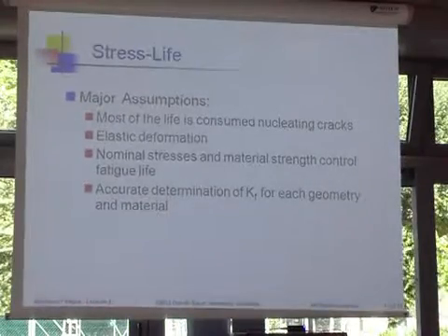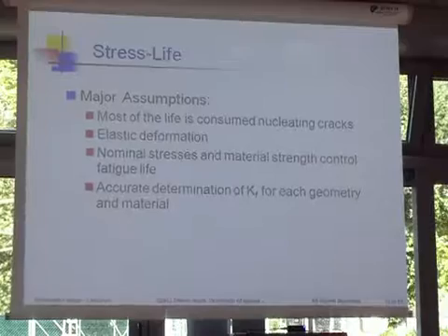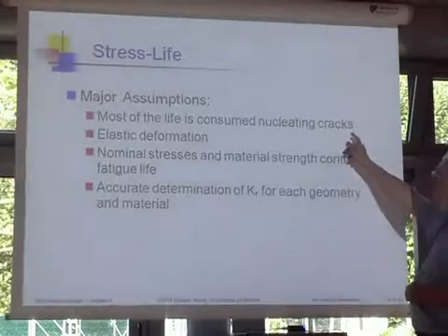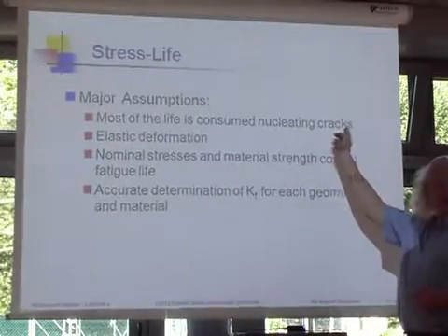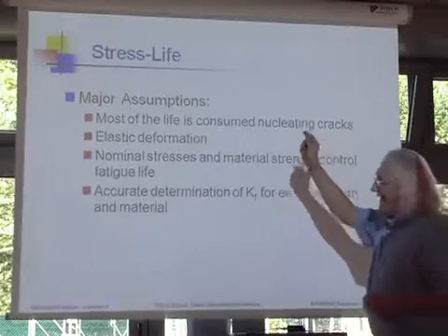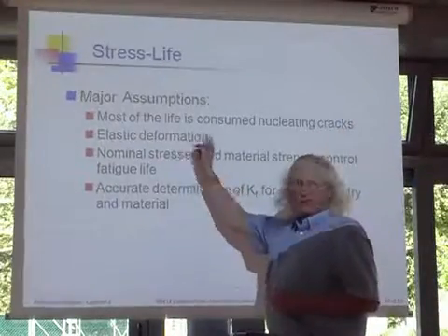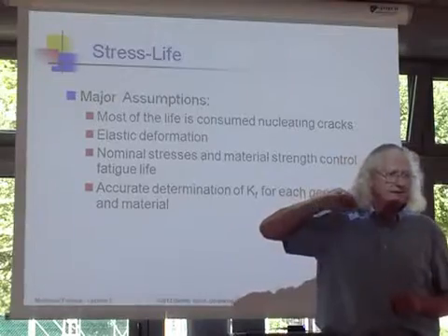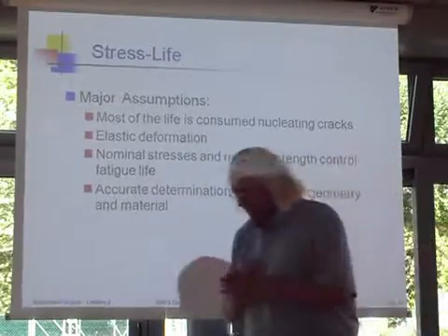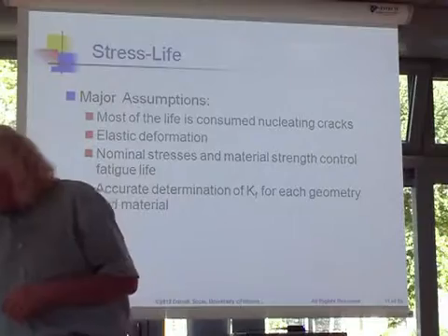So what we don't always think about is the first one. The real assumption behind that is that all the life is spent nucleating cracks. And that means that all the deformation must be elastic. It must always be elastic.